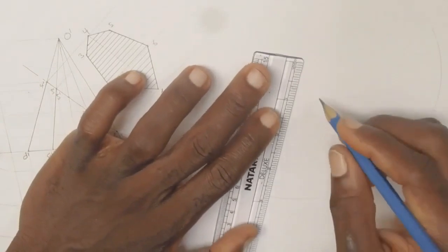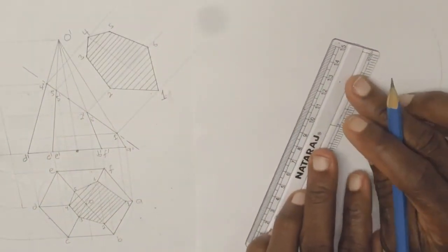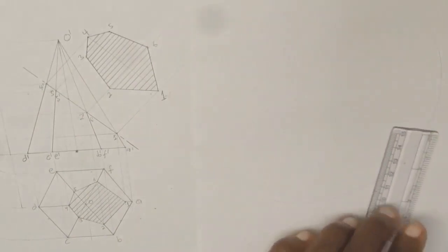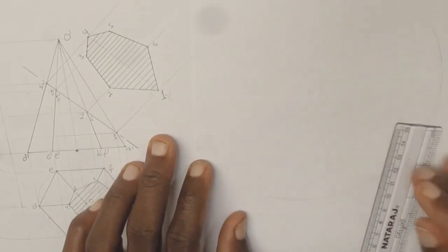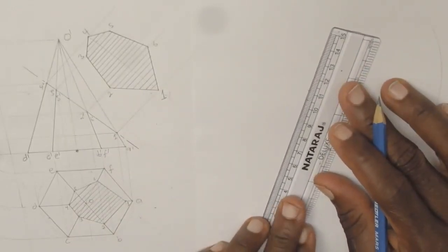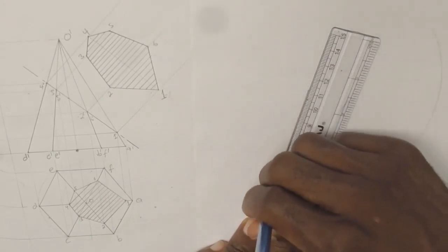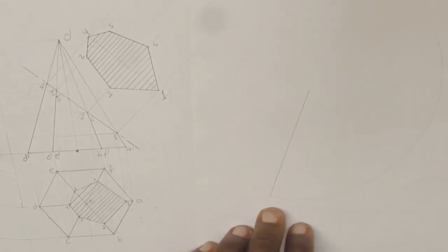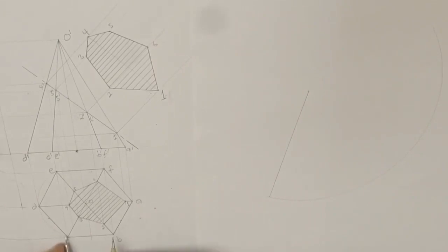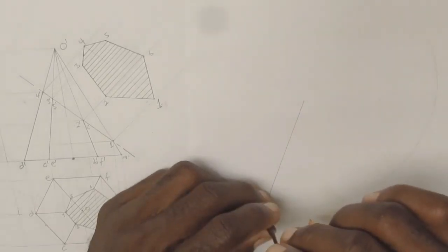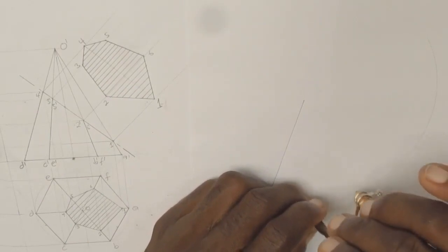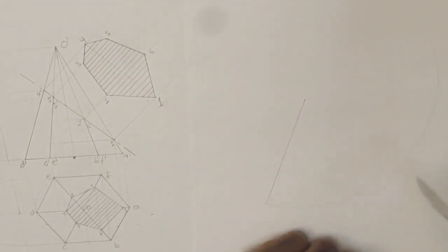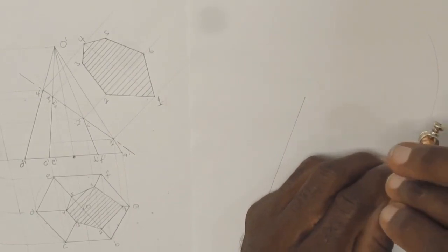Right, so we connect the center of the arc to the end or the beginning of the arc with a straight line. So this will be the starting point for the development. Now we're going to pick the size of the base of the pyramid, which is 30. Then we'll mark it along this arc. Because it has 6 sides, we are going to mark 6 times.